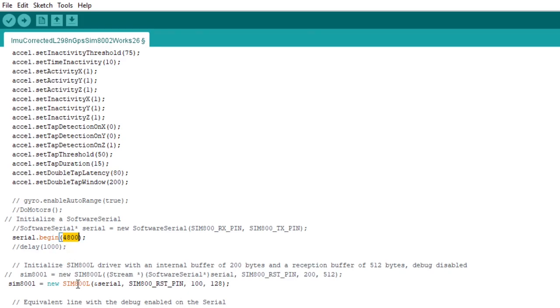Okay, to explain, this is for the SIM800 communication over the GSM network. Now, for it to be able to process information reliably, you want this baud rate to be as low as possible. Therefore the information is sent essentially slower, and it doesn't need to rely on rapid processing to ensure all the information is correct. But the problem is, if you set this too slow, then every time you want to communicate with a SIM800 device, it takes quite a while. Every character is literally, if you halve this, you wait double as long for it to communicate, and there's quite a lot of back and forth communication.